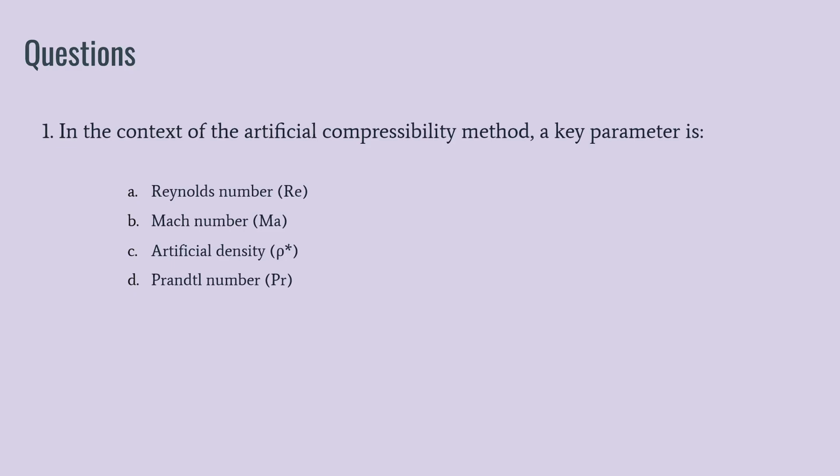So we have gone through the lectures. The artificial compressibility is a concept that will be brought in to couple the pressure and velocities, and to introduce a pressure term to the equations. Because in our continuity equation there is no pressure term for our incompressible flow. For incompressible flow, you also know that del dot u is equal to 0. That is what is governed by incompressible flow.